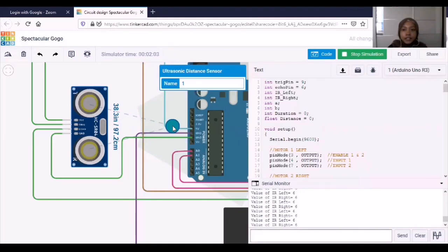For the second, third, and fourth conditions, when the robot and obstacle are less than 65 centimeters, then the robot will stop for 3 seconds, to give the robot time to turn either right, left, or stop. However, in this case of the track, we decide to turn the robot to the right.